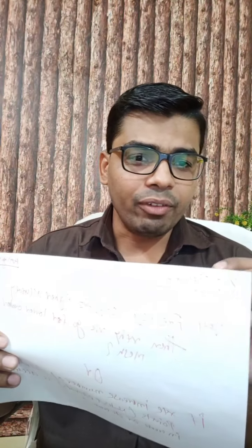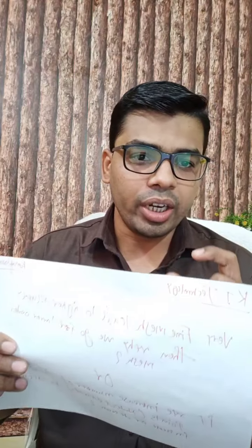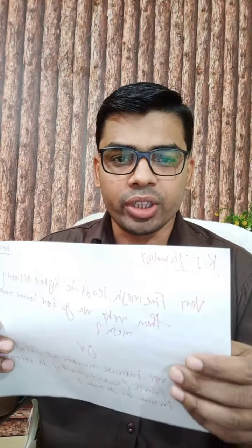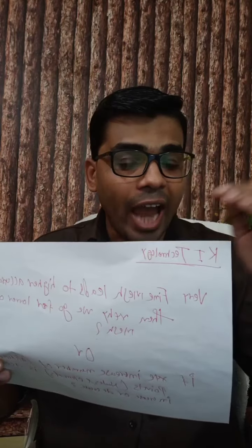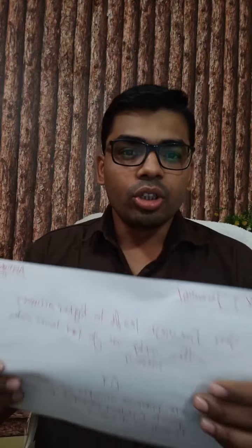So this is a very important question. I'll repeat it once again here. The answer is there in the question itself. If I increase the calculation points, whether the accuracy will increase or decrease. So the answer is yes. If you increase the number of calculation points, your accuracy will increase.